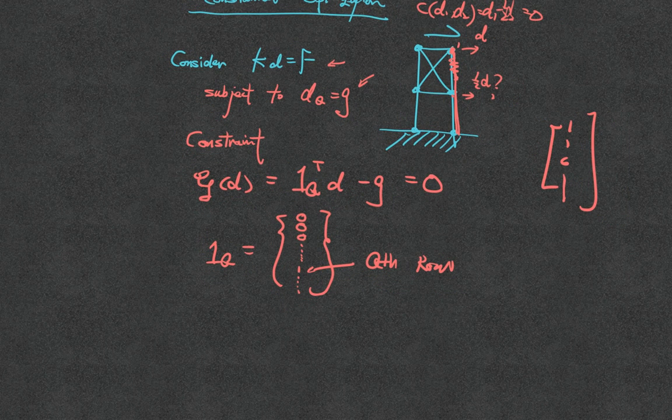In fact, that is perfectly fine. In finite element, in particular in explicit schemes, a lot of the time people use this technique, writing the constraint instead of partitioning the effective stiffness matrix to enforce the essential boundary conditions. This is very common in production code.